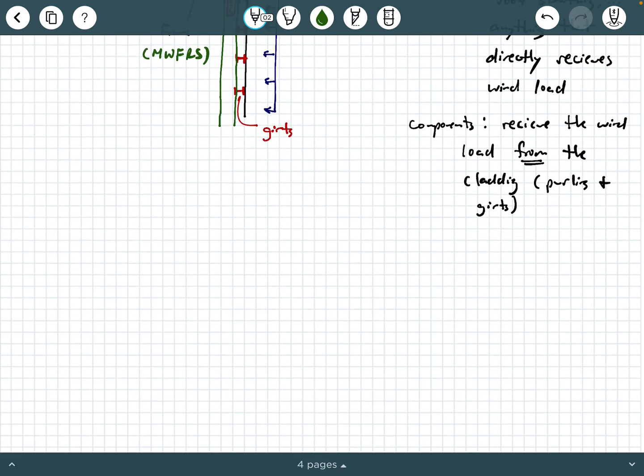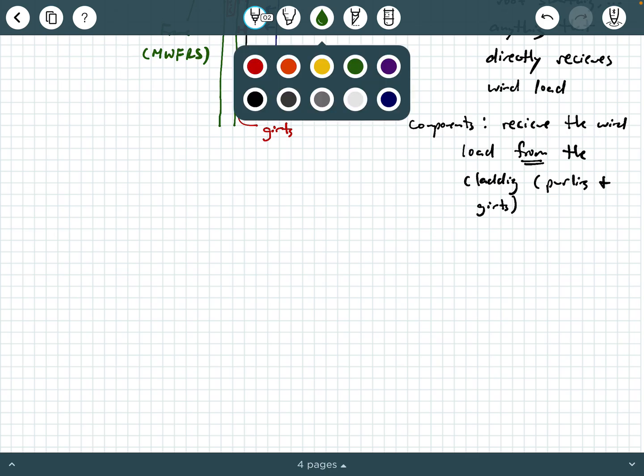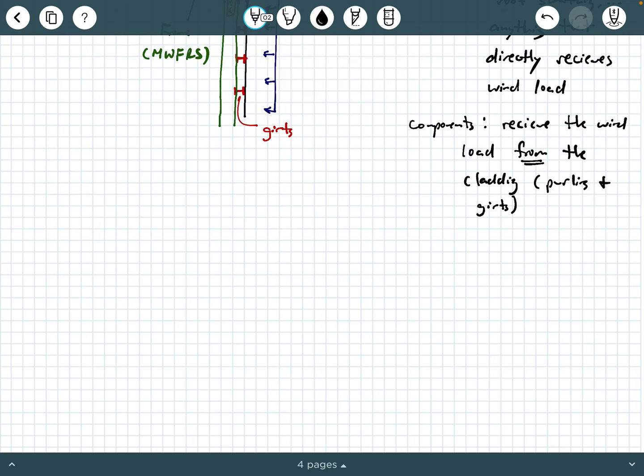The last couple things I want to point out, and then we're going to be wrapping up this video. It's kind of a long video. We have something called the design wind pressure, and we call that little p, okay? So this is the design wind pressure. Now, what does this depend on? Well, it's based on that Q sub Z calculation we talked about earlier. It's based on the velocity pressure that we calculate in chapter 26.